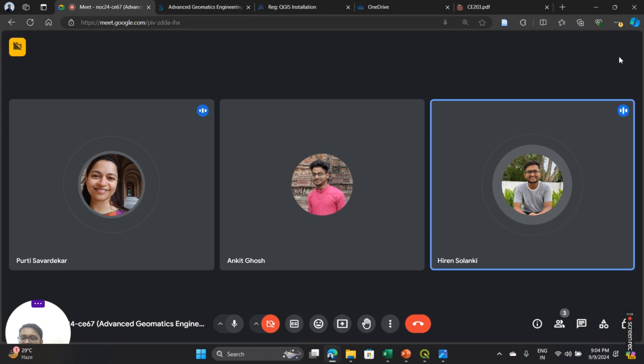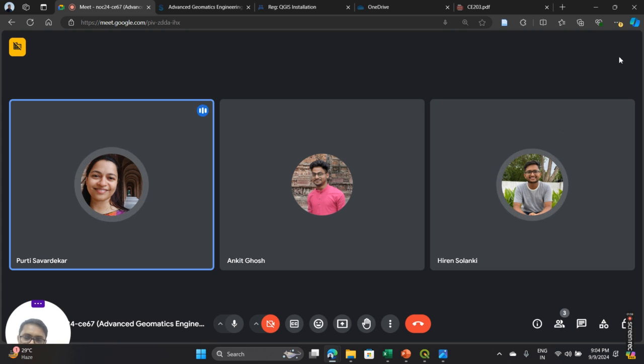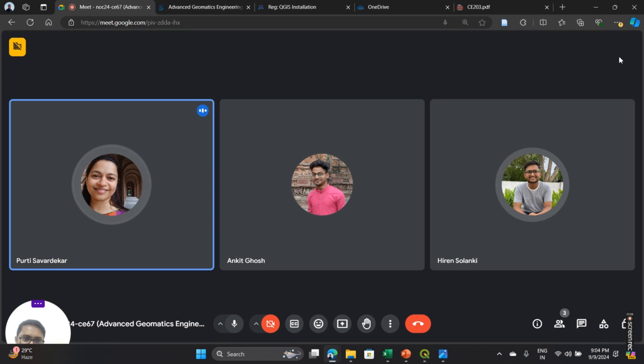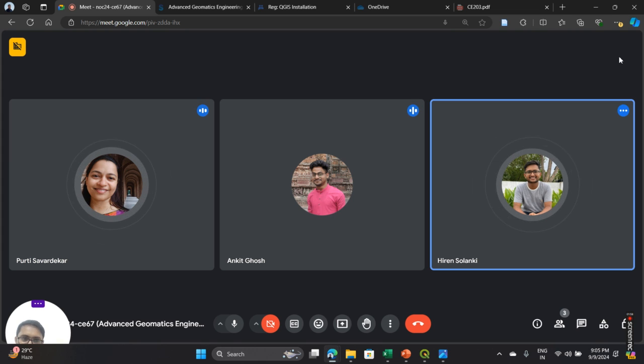Yeah. So for that, it is nothing to do with a fault of digitization. We have to do it manually. The digitization which we can do based on AI will not have that accuracy. We have to do it manually only. So when we are doing digitization manually, it all depends on the base map which we have. If we have Google Map, it depends on how much we can zoom. If we zoom in more, we can do it at centimeter and even millimeter level accuracy as well.